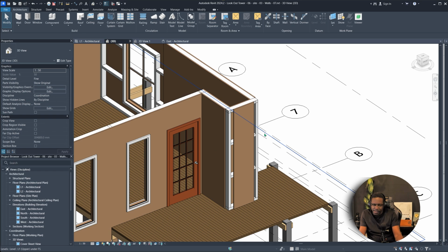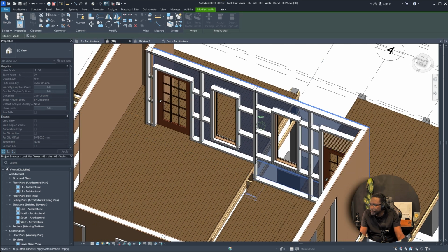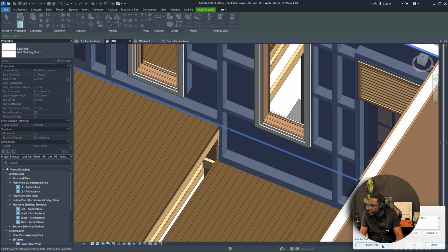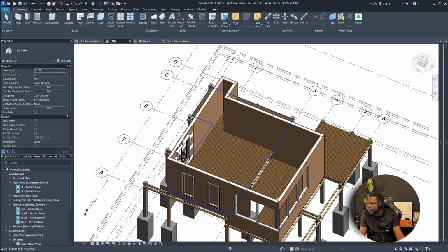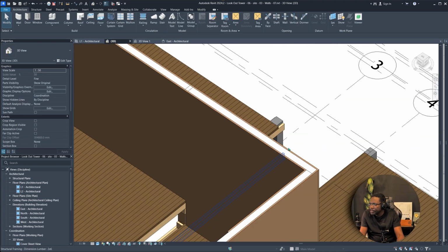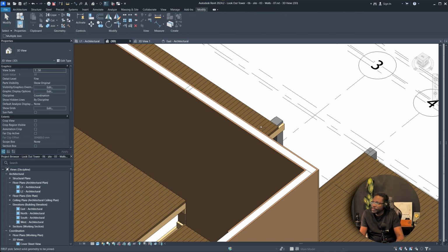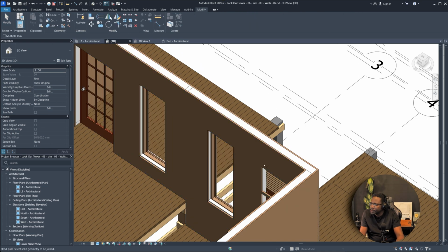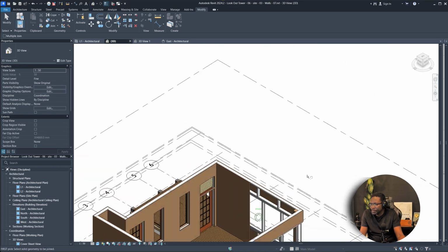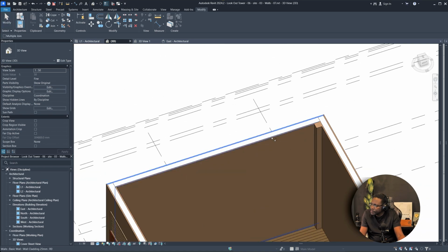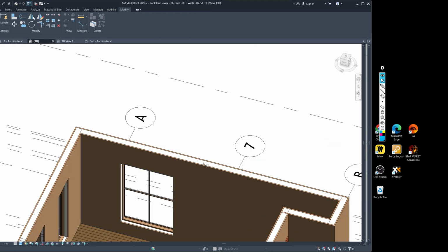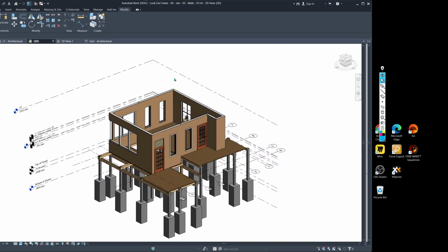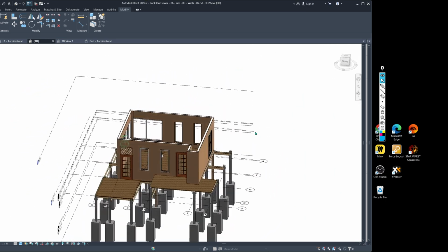All right, now we can deal with the internal walls. Okay, we can use this one. It also duplicated the windows as well, so we don't need that. Now what we're going to do is attach these together using the join tool. We're going to join this wall with this wall, and that will automatically give us all the cuts. So let's join this wall with that wall, and this wall with that. All right, and with that, those are the walls that we have.